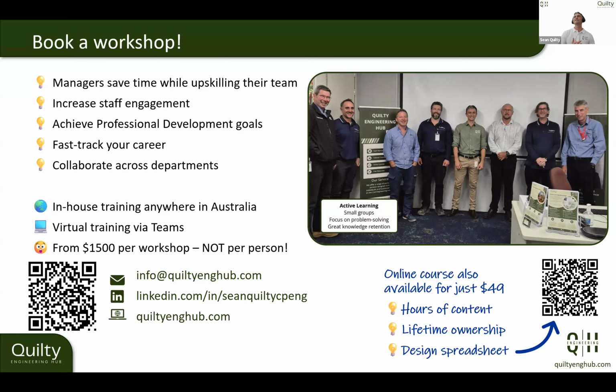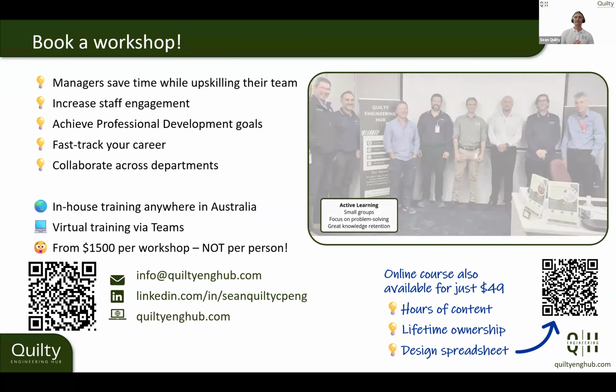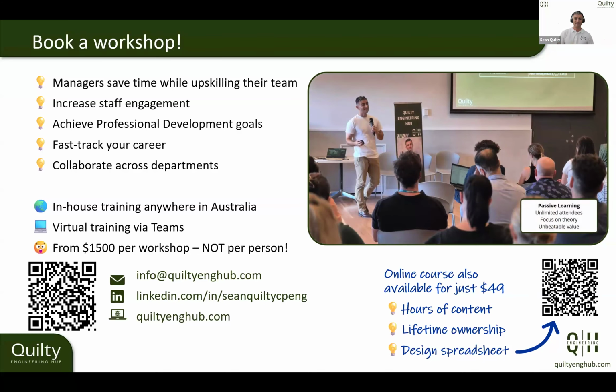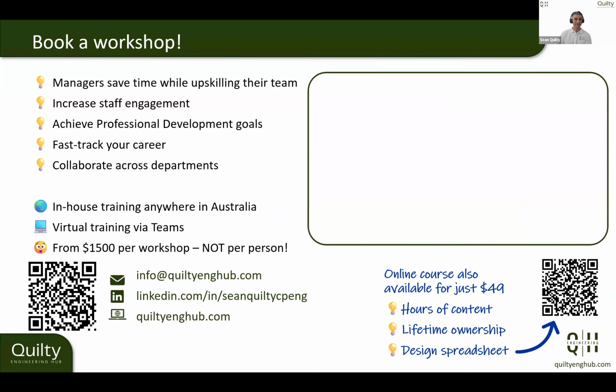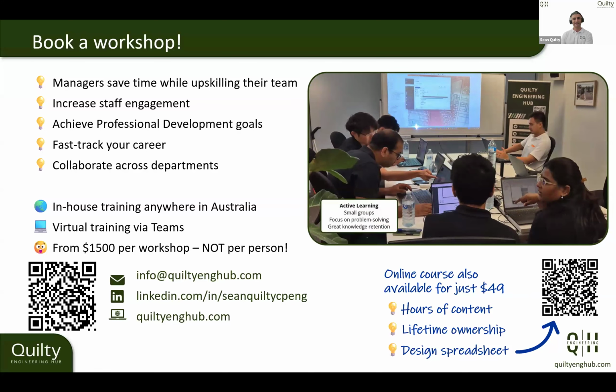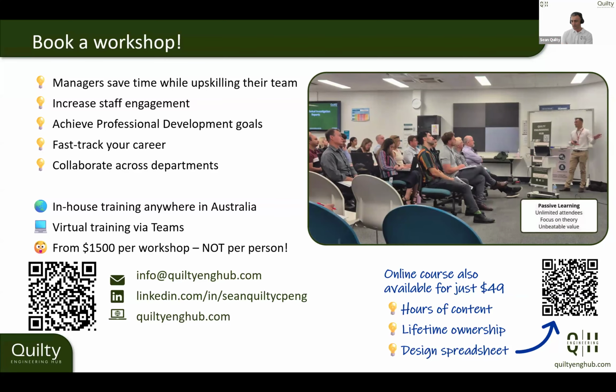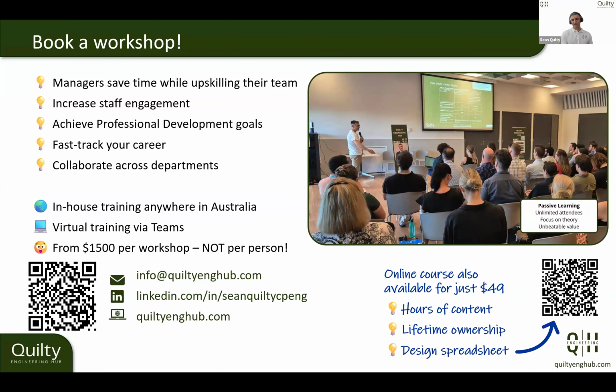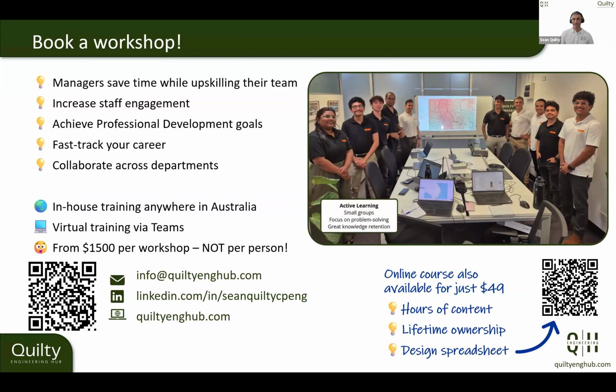All right, energy dissipators. This one's interesting because there are some guidelines. Some people might have heard of the HEC guidelines. I think, don't quote me, it's HEC-15. If you Google that, that's a standard they use in the US for their highway design. And I'm pretty sure there's a big section in there on energy dissipators. If you wanted to do it properly, there are some equations, and they're actually very good examples of different configurations of energy dissipators.